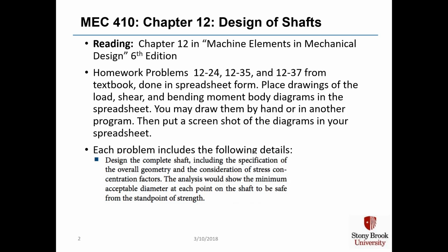You don't have to create CAD drawings for load, shear, and moment body diagrams. You just hand sketch them, take a scan, and pop it into your spreadsheet. Each problem does include, however, doing the complete shaft design, which includes the specification of the geometry. You have to do free body diagrams, go figure out all the forces.